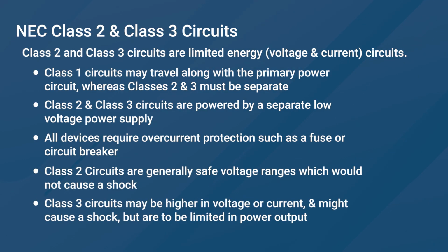Class 2 circuits use a voltage and current which would not present the risk of shock, but Class 3 circuits can be of a higher voltage which would represent a shock hazard. Overall, however, both Class 2 and 3 are generally considered to be low-power signals.